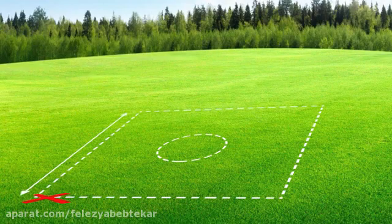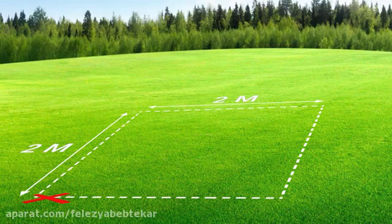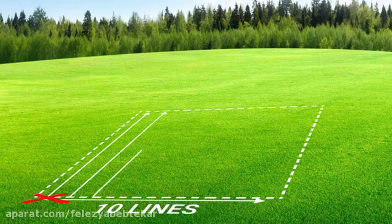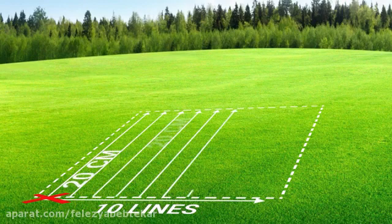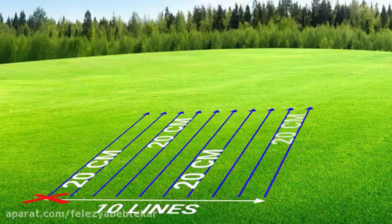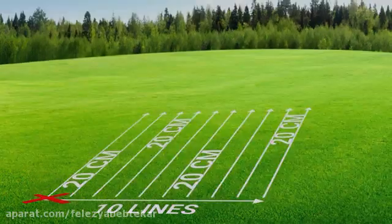After selecting the location of the scan and determining its dimensions, in our example, a ground with dimensions of 2 meters by 2 meters, determine the distance of the scan lines based on the dimensions of your scan. By line, we mean the direct routes on which the scan is performed so that the entire selected location is covered by our scan. We divided it into 10 lines of 20 centimeters. The smaller the line spacing, the higher the scan resolution and scan accuracy.